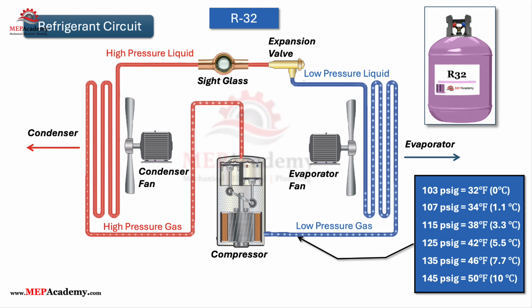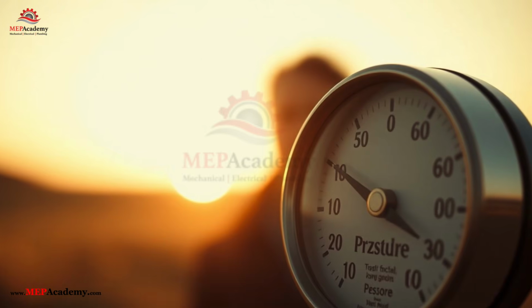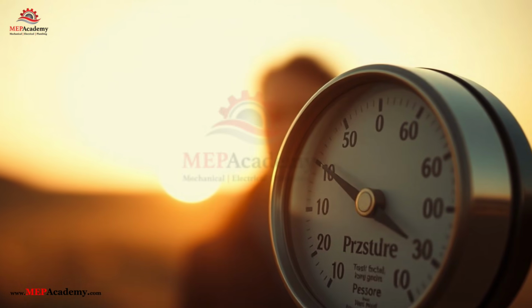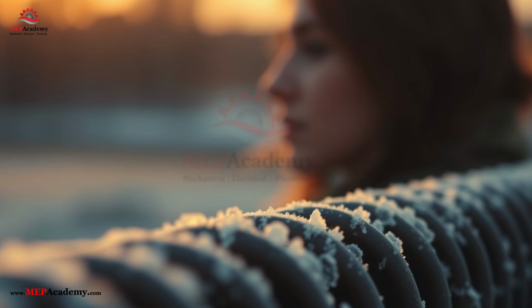In most air conditioning and refrigeration systems, normal suction pressure typically ranges between 60 to 85 psig, 4.1 to 5.9 bar for R22, or 120 to 145 psig, 8.3 to 10 bar for R410A, or 115 to 145 psig, 7.9 to 10 bar for R32, depending on the system and ambient conditions. When this pressure drops too low, it usually means the system isn't absorbing enough heat. But the reason why can vary.